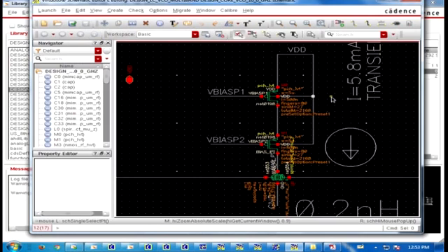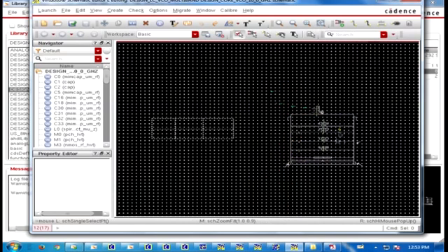These are the cascoded transistors. It is giving current to the total circuit. It's a huge transistor. Its W is 1440 fingers, and the finger length is around 5 micro. So it's a huge transistor. Threshold voltage is around 0.4.